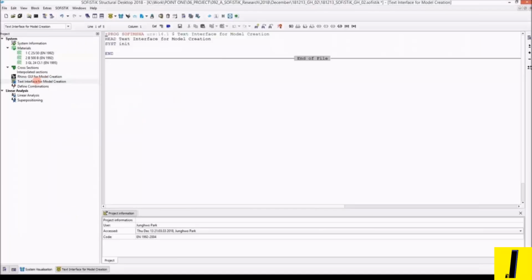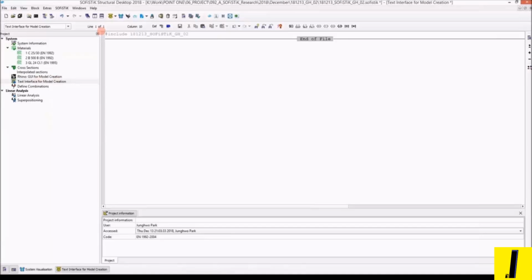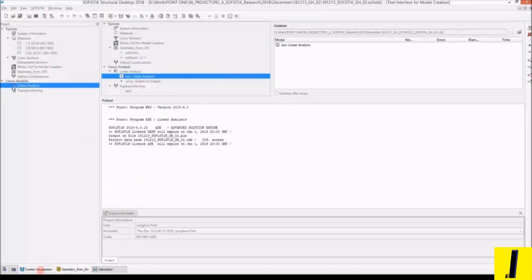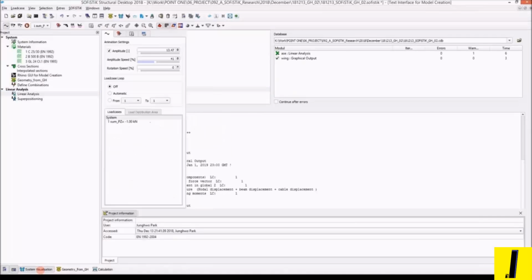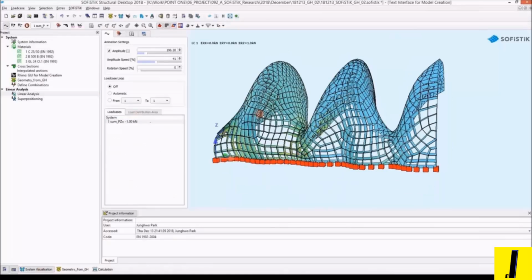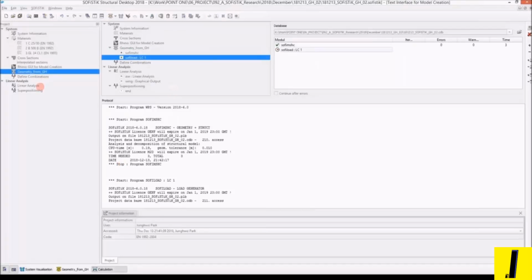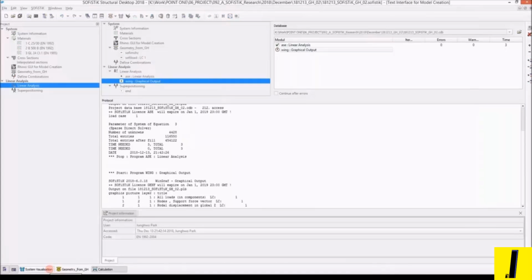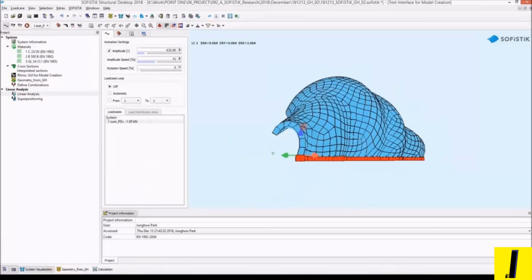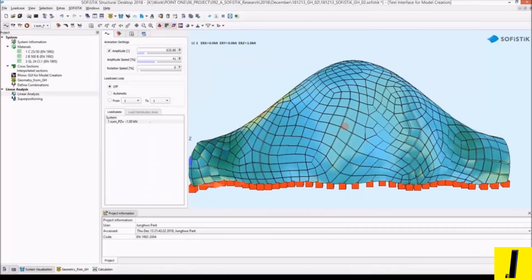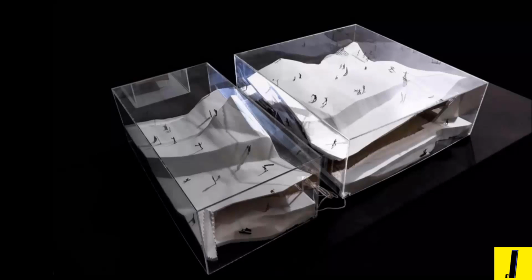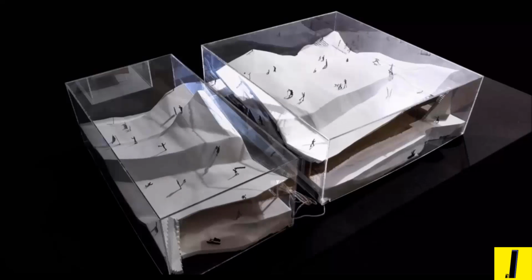And with a text format, here we can type include and then the same file name in the same directory, and then you can calculate the geometry from Grasshopper. And at that moment, I just gave a simple dead load, but we can obviously define a point load, and all kinds of flexibility using text input in SOFiSTiK or Grasshopper, different load case definitions.